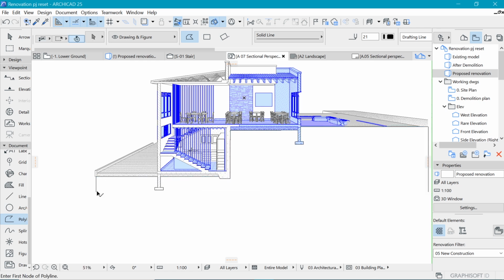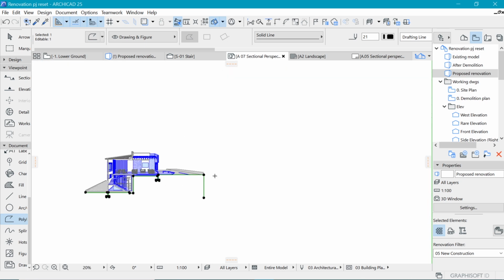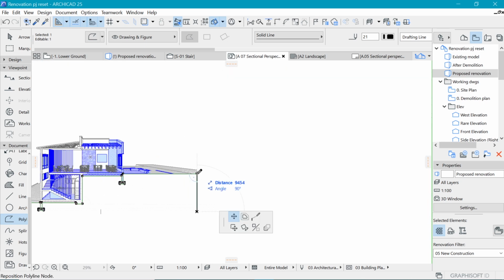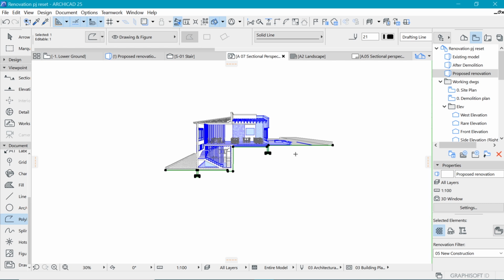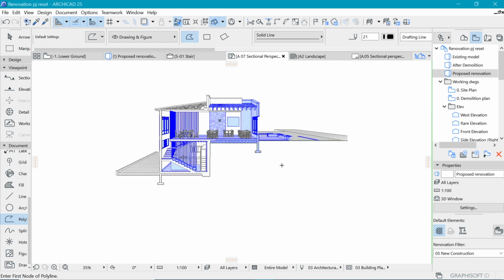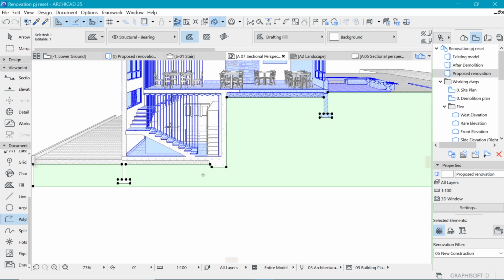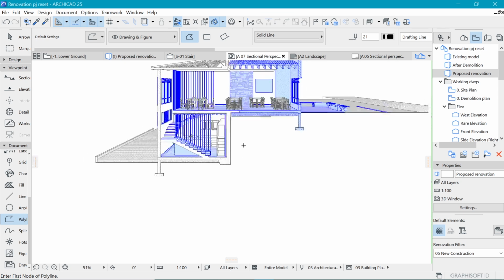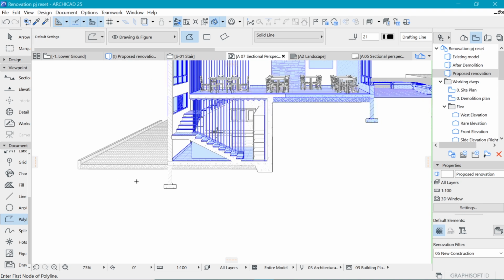Then we can remove it from the sections which are under the drawing to just have that ground level line there, and there we have it. So this fill is helping us hide the things which we do not want to see in this particular drawing, and that gives us the opportunity to draw the things which we actually do want to see.